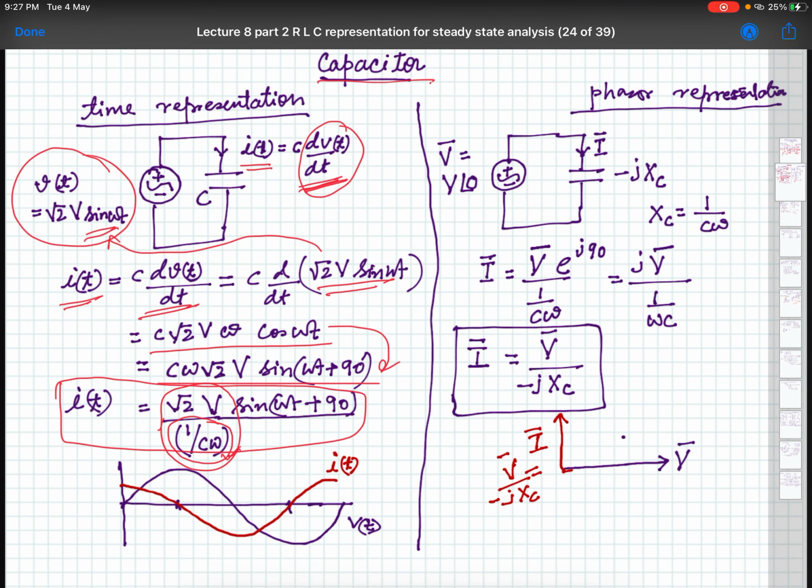This is one thing which happens, and the other thing is there is a phase difference. Having a capacitor in a circuit gives currents that are divided by a certain value, and it also shifts the waveform. The current is shifted by 90 degrees in a capacitor, and that shift is called a leading shift because it is plus here.